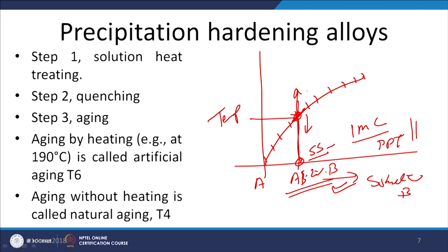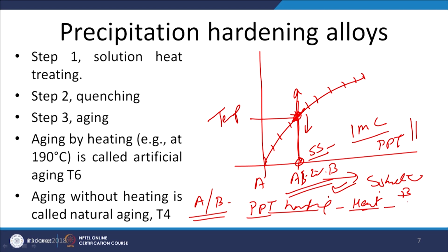So, to form a metal having elements A and B, which is designed to get strengthened through precipitation hardening, when such a metal is subjected to heating above the solvus line, it forms a solid solution. The process of forming the solid solution through heating is called solutionizing.